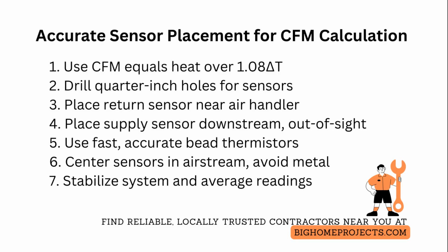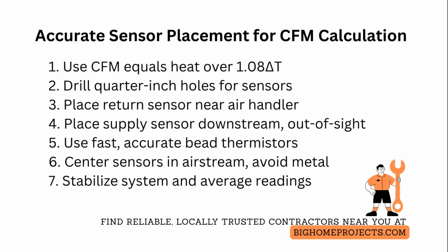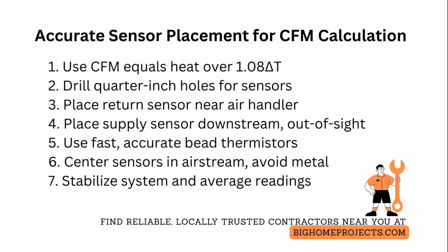Correct for electric heat staging by confirming which strips are energized and using the actual kilowatts from clamp meters and voltage readings to compute total heat output. Then confirm nameplate versus measured kilowatts match within 5%.